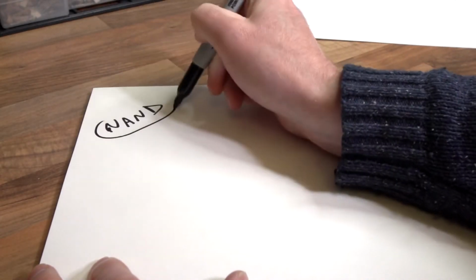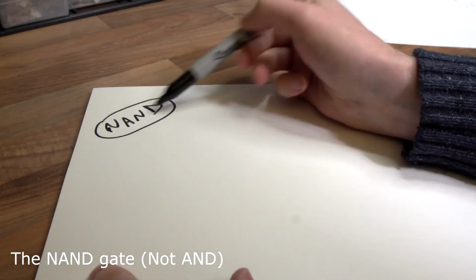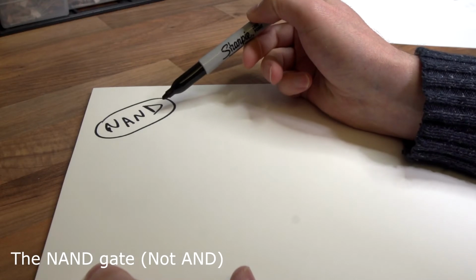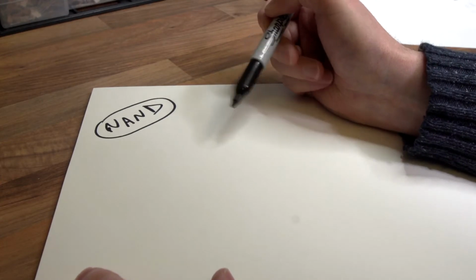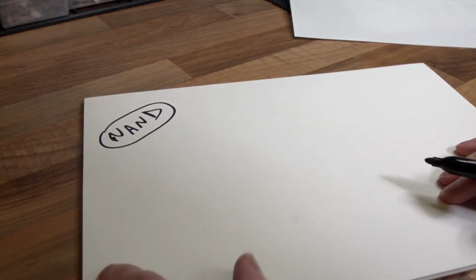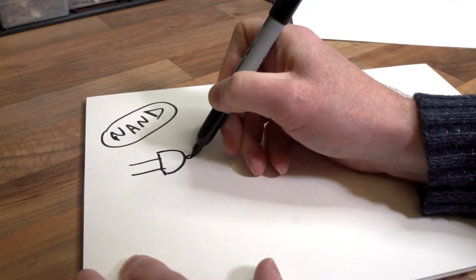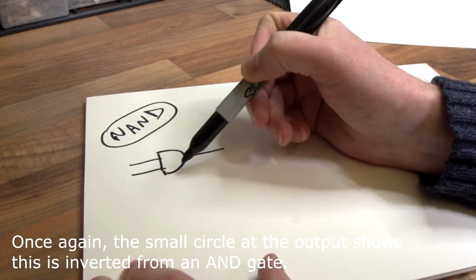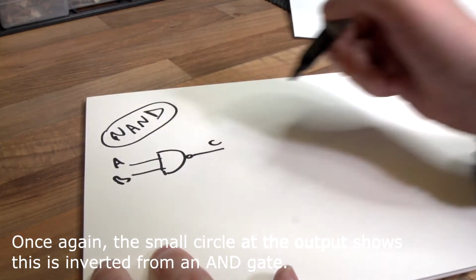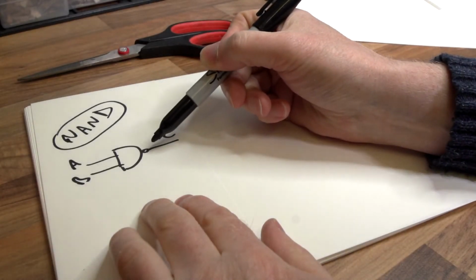How about a NAND gate? Here's another one. Now a NAND gate, you've probably guessed it from the NOR gate. The N means not and. So if you remember on our AND gate, we had the two switches in series. A and B had to be both on before you got an output. But with a NAND gate, it's the opposite of that. And the symbol for a NAND is like that, with a little bobble on the output. That's an AND gate, and it has a straight edge to the front to make it separate from an OR gate. That would be A, B, and that would be our C output if you like. So that's our NAND gate with our circuit diagram with a little circle on the output symbol.